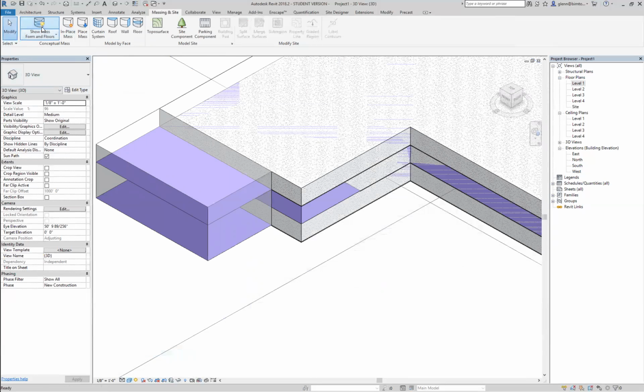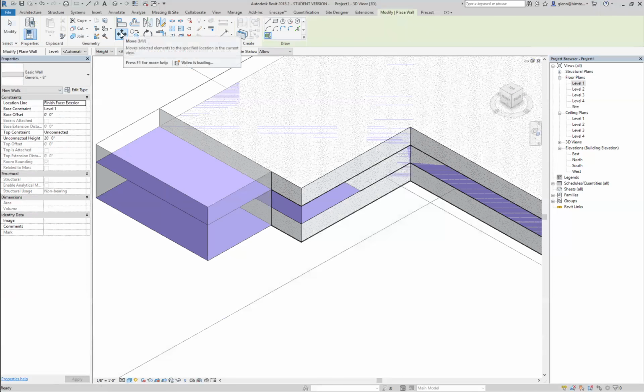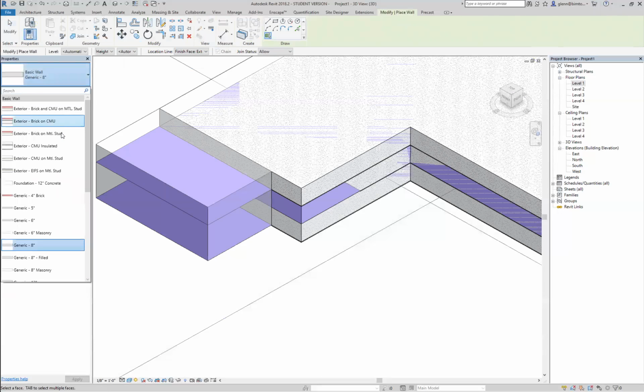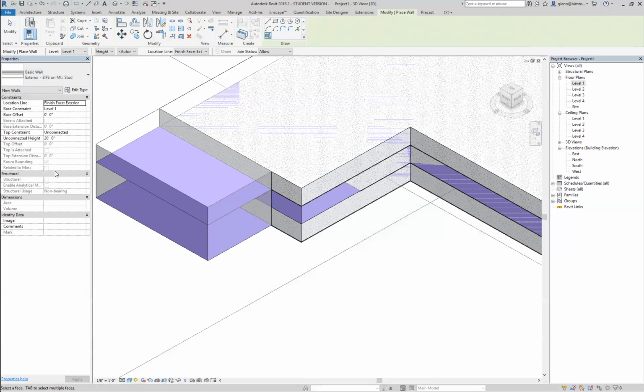Another thing we showed last time, which is a handy way to do this, is you can go through and take a wall, and again, you should always think about the proper surface. I'll make it this EIFS. You have the choice of, is this surface going to represent the core or the finished face? And I usually make it the core. And I can drop some walls on there.